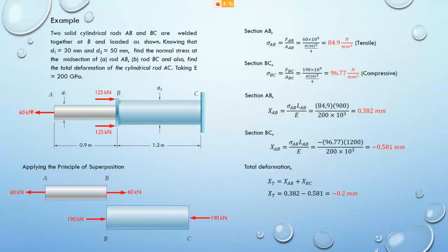So just pick up the force here at the outer edge. The reaction at C here you don't know yet because you don't have any forces acting here in the diagram. But first we have to find out what is the force that is acting here. Actually, you can do it by taking the equilibrium of the whole assembly.